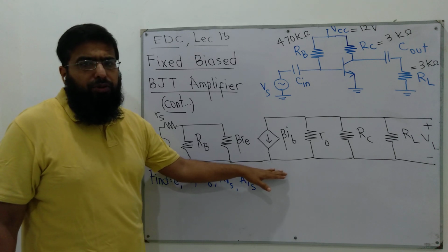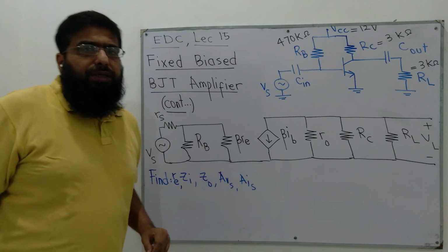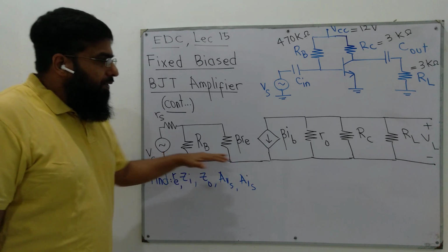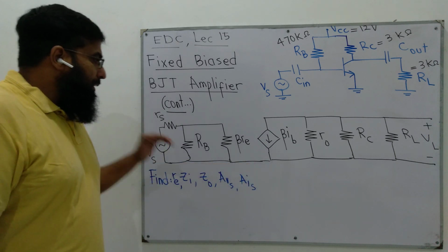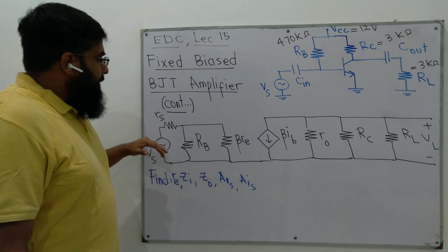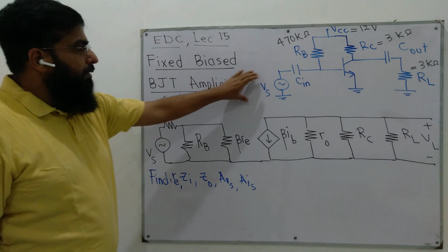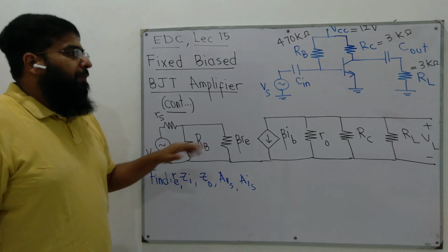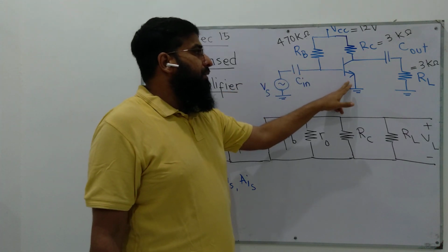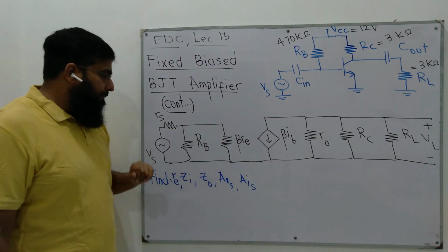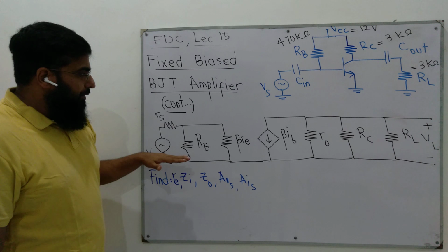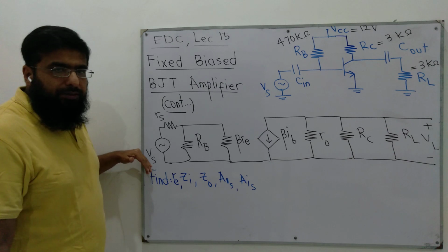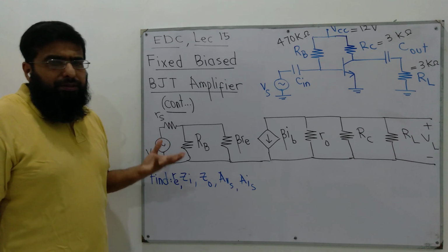using basic linear components so that the laws and theorems of basic circuit analysis can be applied on it. This is the equivalent circuit that we drew in the last lecture, and we studied how the input side, the AC voltage VS, sees two resistors in parallel. These are RB and this re, the junction resistance multiplied by beta if seen on the base side. They appear to be in parallel with each other, and we have this small resistor RS, the internal resistance of the source, which is very small, and in many cases it is negligible.